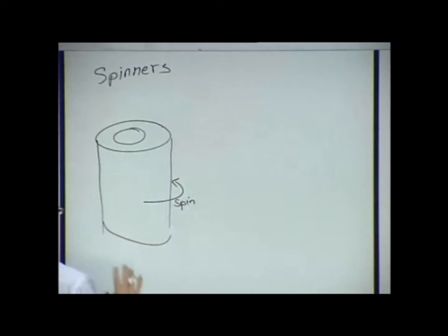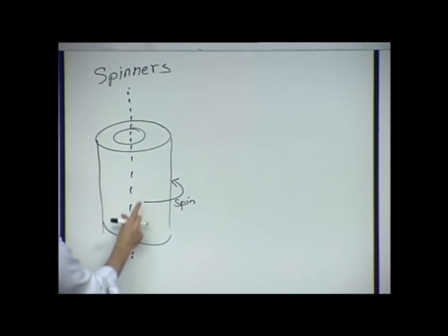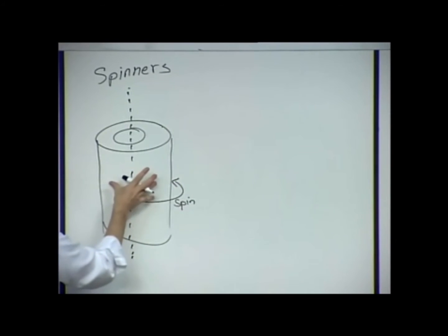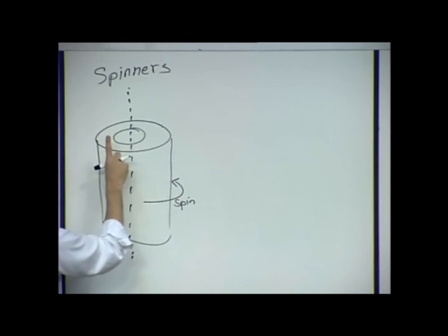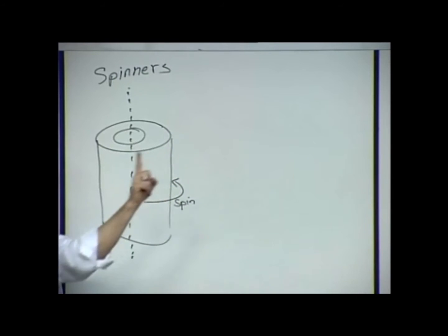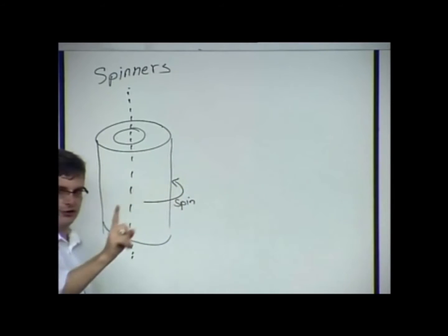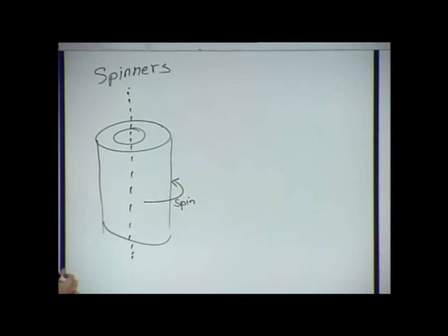Because basically, when you spin this, this imparts angular momentum along an axis, and this satellite will hang there, and by conservation of angular momentum, will stay oriented along there, not unlike a gyroscope, as it revolves around the Earth. And so you don't really need a lot of fancy attitude control systems once you've done that.